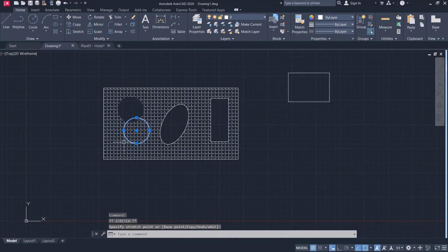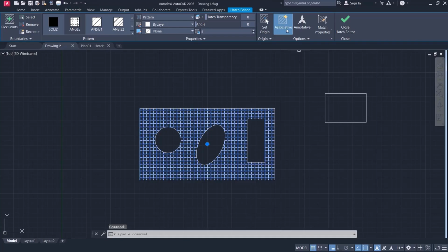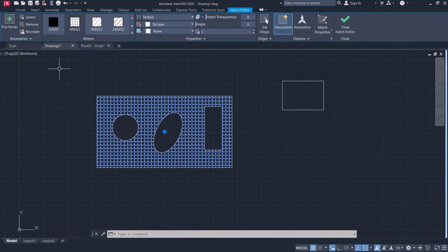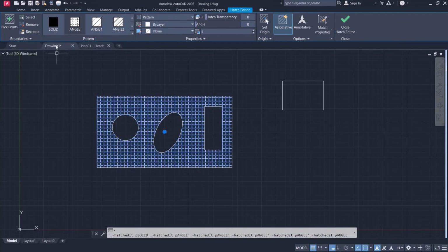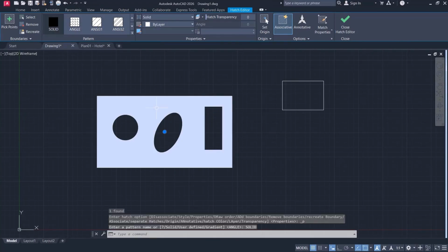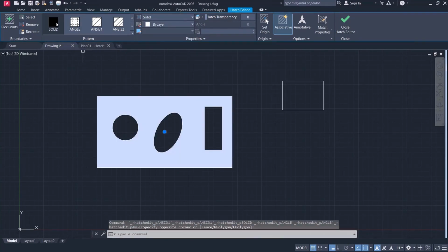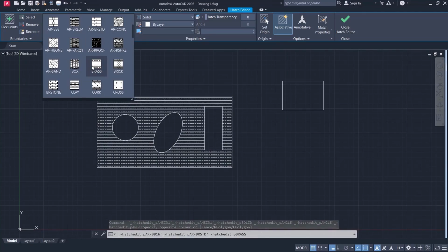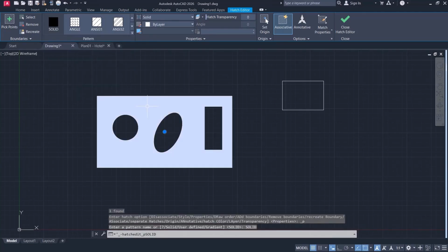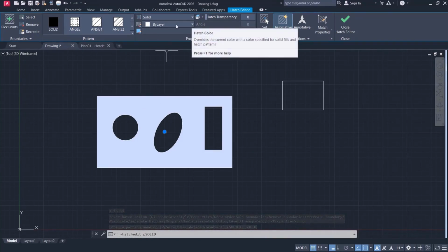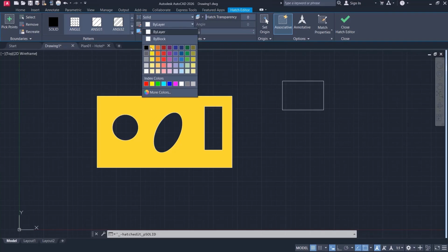It has many uses. The next options, we can use patterns, colors, or other settings. If we select solid, it becomes a solid uniform color. The solid color can be selected here, whether it's solid or patterned. Again, I can open the pattern list and select a pattern or a solid color. For now, I have a solid color. How can I specify its color? It can be by layer, matching the layer it's on, or another color, like yellow or green. This type of green or these colors are enough for me. It uses index color, which are specific, typical colors.